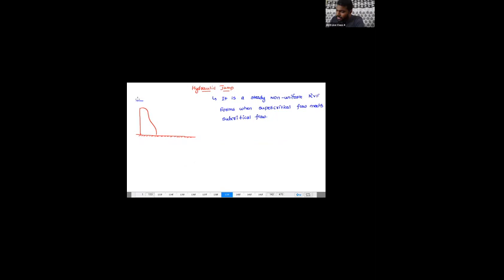You know, this is the water level on the upstream. And from here, if I open the gate, then the water falls, and this is nothing but the nappe, and once it falls, this is the vena contracta, the minimum cross section. It is going to form a minimum cross section, the vena contracta, and then the water level is going to rise and form a third profile, yes or no. And somewhere there must be the CDL, and below the CDL supercritical flow.